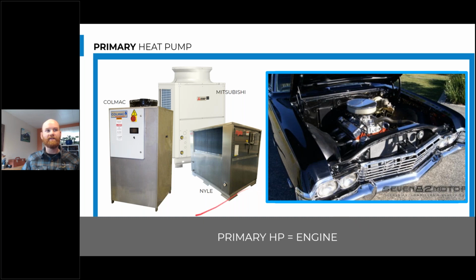And shown here on the screen are 3 large commercially sized heat pump water heaters that are great for a variety of different applications. We have our Colmac heat pump water heater, which is using the refrigerant R134A. We have a Nile heat pump water heater, which is also using R134A as the refrigerant. We have a Mitsubishi that's using CO2 or R744 as the refrigerant.